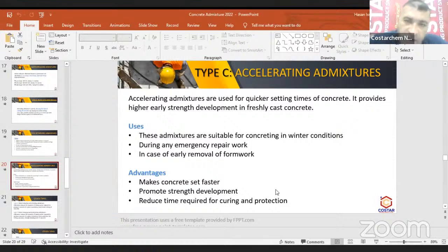Type F, there'll be no retardation. It will be a moderate early compressive strength, and also an acceptable later strength. Type G will be slow in the beginning, still acceptable early compressive strength, but the best reading you will get is from type G.